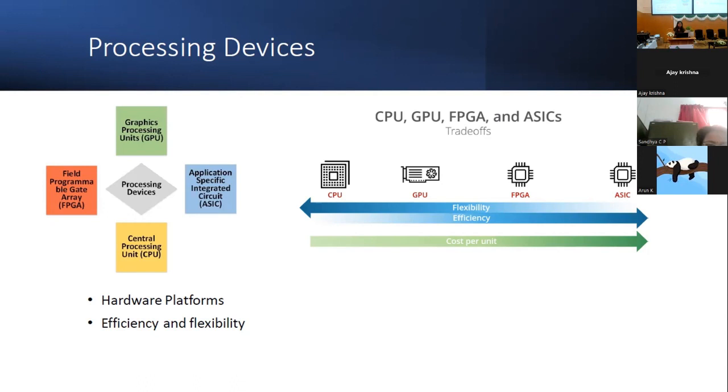Why? Because in FPGA, we can interconnect things, but how we interconnect depends on the efficiency. Also, the hardware parts are aligned in a particular way. We cannot interconnect so that the data will move from one place to another that fast. But ASIC means for one particular application, I'm building the hardware. So I can keep, suppose, memory near my adder, keep certain memory locations near my computational unit. So we can make it faster. That's why ASIC is faster than FPGA.